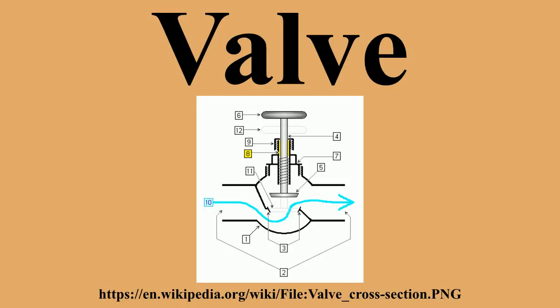Valve bodies are usually metallic or plastic. Brass, bronze, gunmetal, cast iron, steel, alloy steels and stainless steels are very common. Seawater applications, like desalination plants, often use duplex valves, as well as super duplex valves, due to the corrosion-resistant properties, particularly against warm seawater.